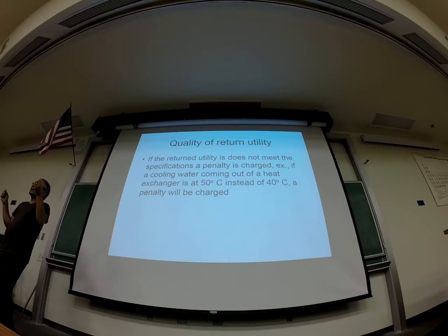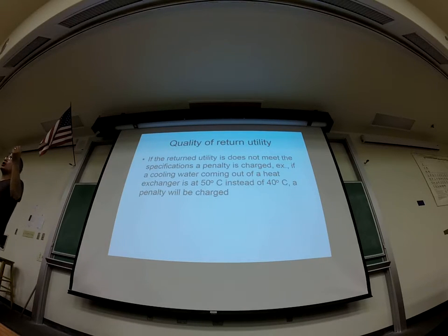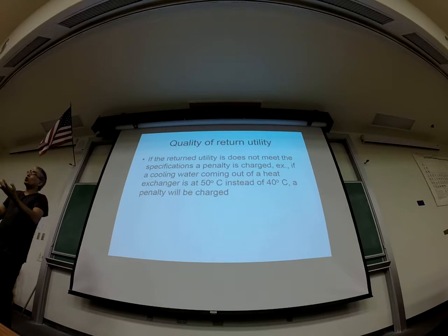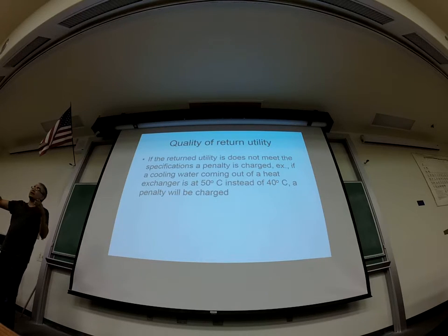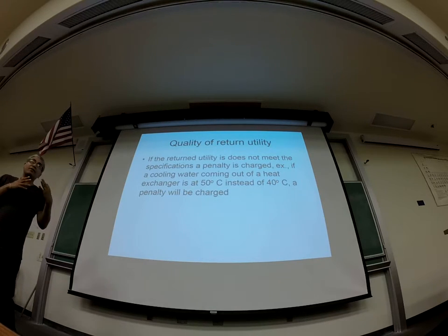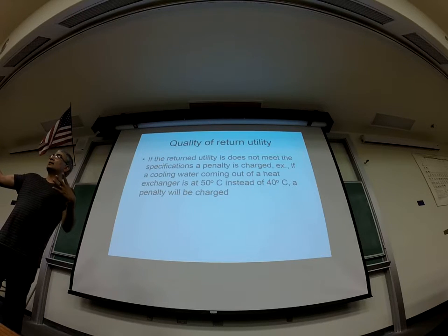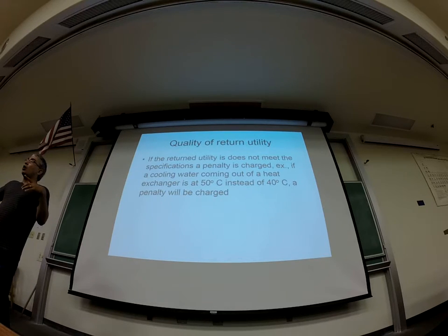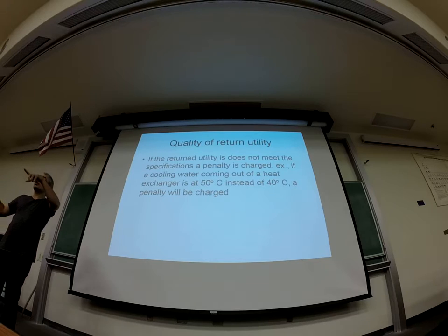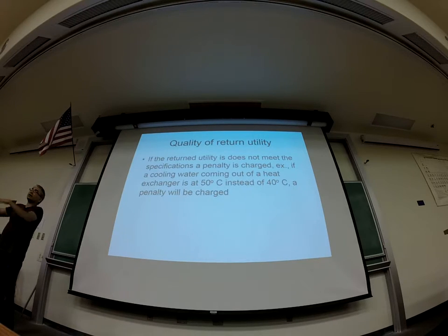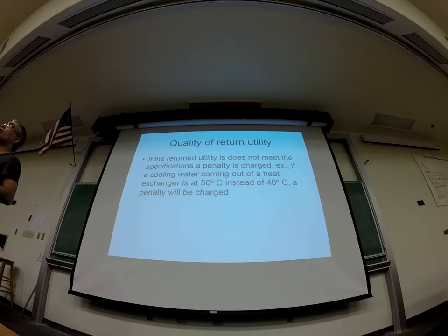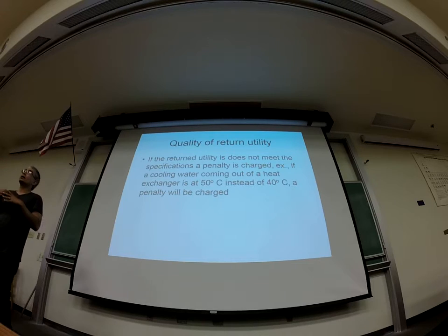what is the advantage of keeping your outlet temperature very low? Now the lowest you can of course go is the outlet temperature of your process stream, right? If your process stream is heating from, let's say, 30 to 60, the lowest temperature you're going to allow your outlet of your hot water to go to is 60, right? But you don't necessarily want to go to 60. If you want to go to 60, what's going to happen to area? Area will actually be infinity, right?